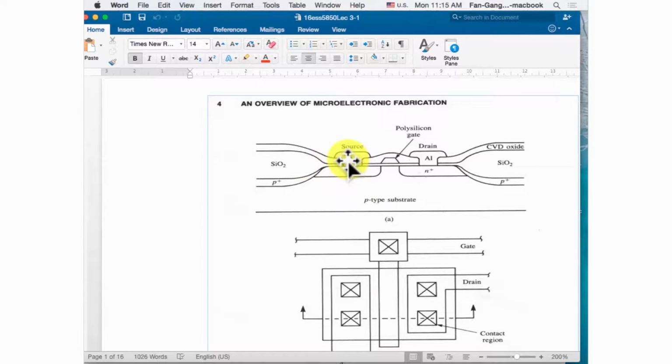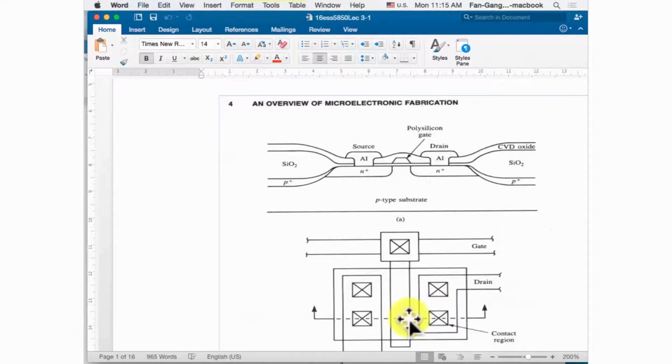So for example, you want to connect the aluminum wire to the bottom electrode. The current bottom electrode is a highly diffused, highly doped area. So the area contact was through a small window here, right? The cross area, you can see here is an opening area for the contact from the top electrode to the bottom electrode.